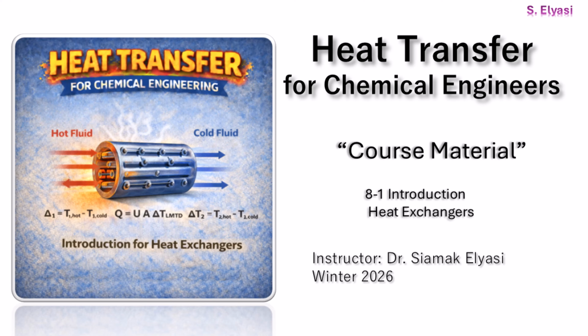Okay, second takeaway. To get the U we want, we mainly use three types of equipment. There's the really simple double pipe setup, which is great for smaller flows. Then for big, industrial-scale jobs, you've got the shell and tube exchanger. This one's smart. It uses internal walls called baffles to make the fluid move across the tubes to really maximize that heat transfer. And finally, there's the cross-flow exchanger.